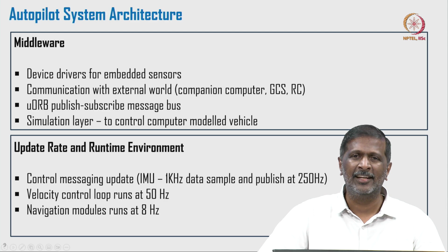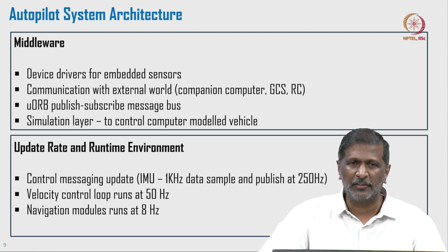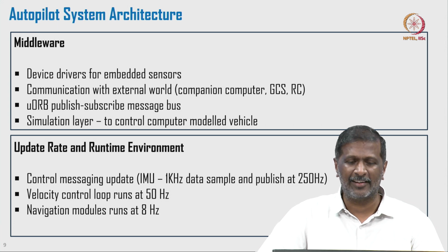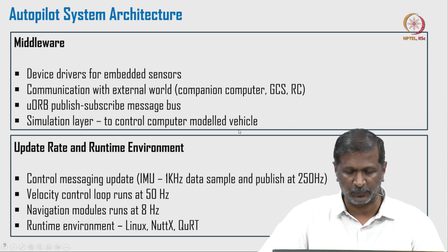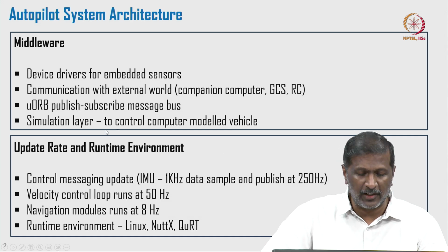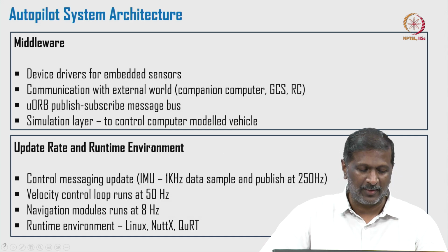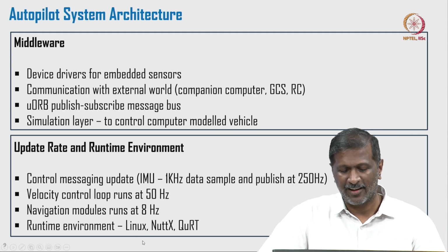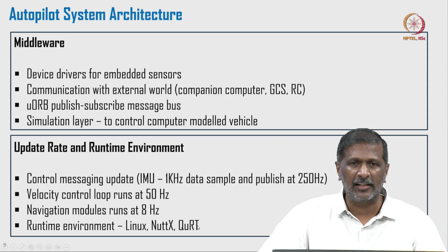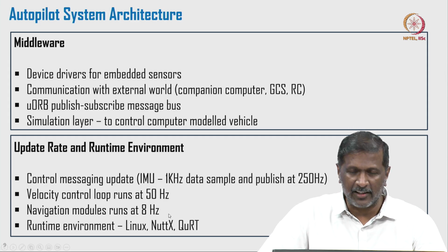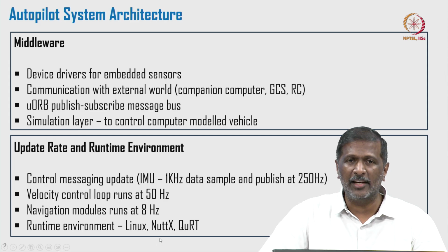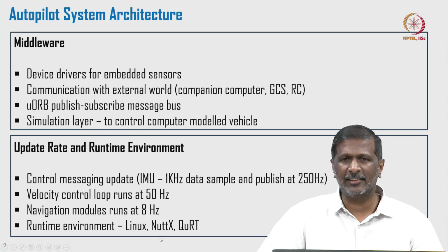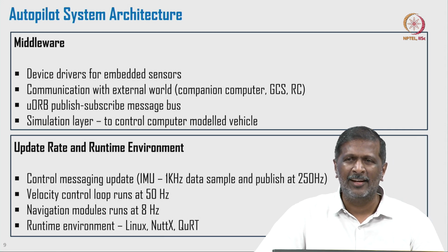Understand what the system frequency is, how we have to read this signal and how we have to send it, so that my motor can act quickly, right? All these are important factors, right? And all these have to run on a microcontroller. The runtime environment is also important, right? I can run it in Linux, or I can run it on NuttX and QNX, right? These are RTOSes, real-time operating systems, right? So I need those. I don't need unnecessary control in my operating system. It should be real-time, right?